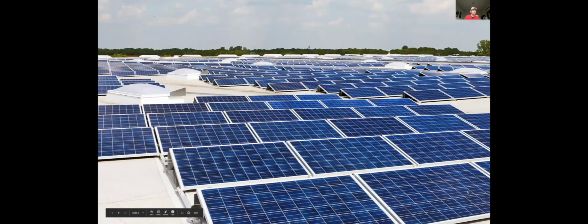The next big thing is solar panels. This is the most common way of generating power in a CubeSat. People have proposed nuclear power. I think that's highly unlikely to ever happen, but pretty much when you have a computer, you need a power source and you need to generate that power. And so we use solar panels. Typically these would be space grade and fancy. Sometimes they have integrated electronics on them for moderating the power flow, but typically that would be handled in the power subsystem of the satellite.